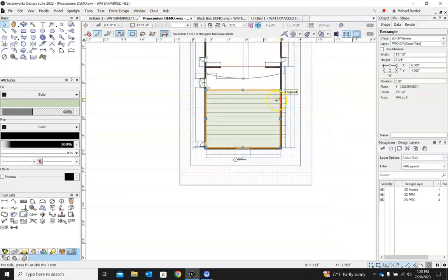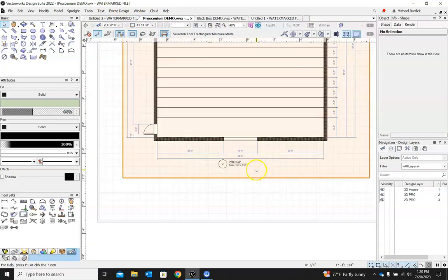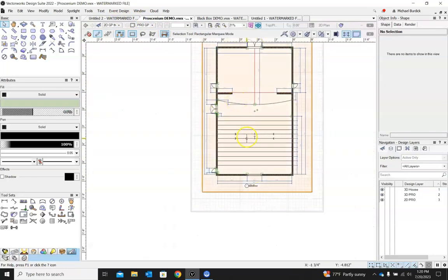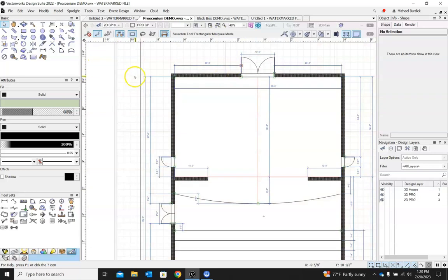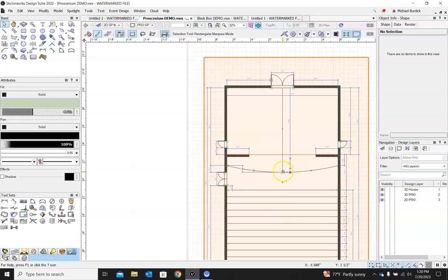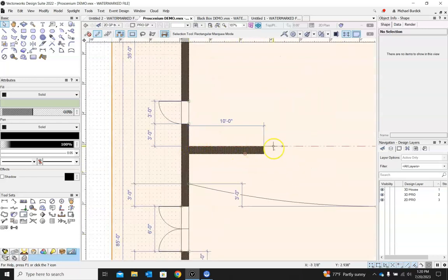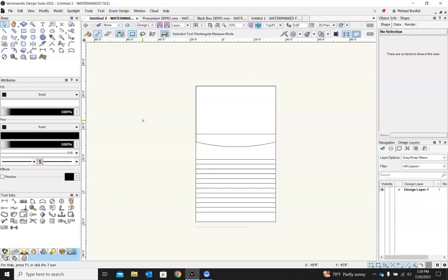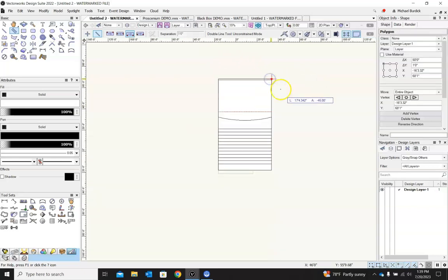Let's go ahead and drop in our walls. You'll note on here that all of the walls are 1 foot thick. And they basically go around the entire perimeter, and then they come in just downstage of your plaster line. And those are 10 foot long off each side. So now I'll grab my double line tool, just confirm that it's set for 1 foot wide, and then I will just start making little walls around here.